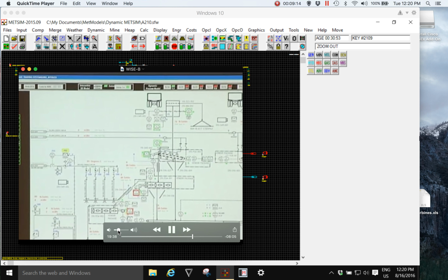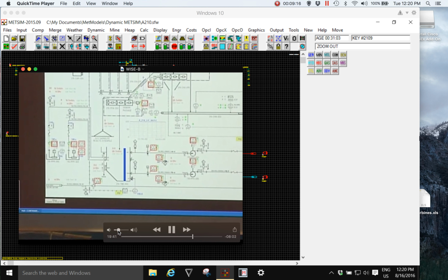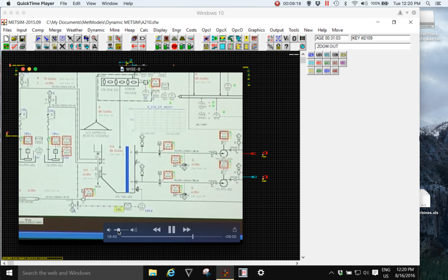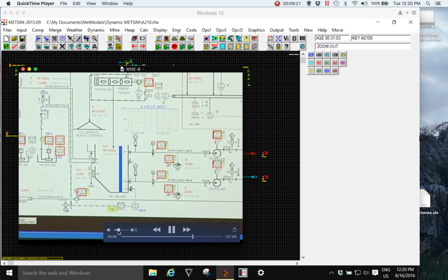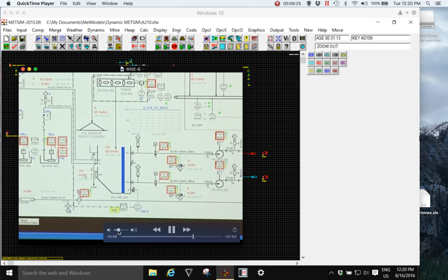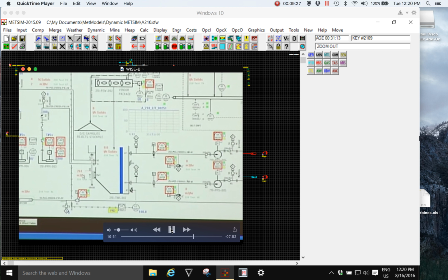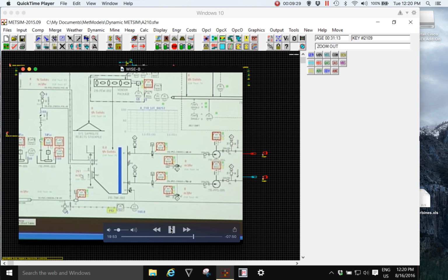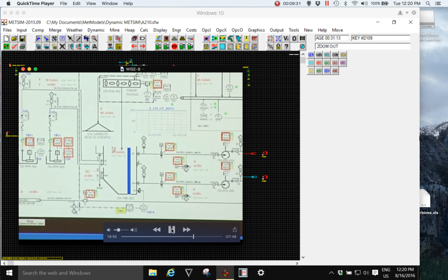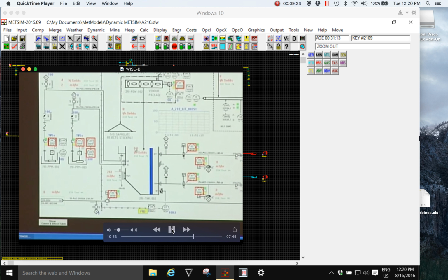And I can see on this hopper where we're pouring in water at 255 meters cubed per hour, without taking anything out, that it's overflowing at a rate of 261 meters cubed per hour. It's not quite balancing. There must be something coming in from somewhere, or the instruments are not perfectly calibrated.